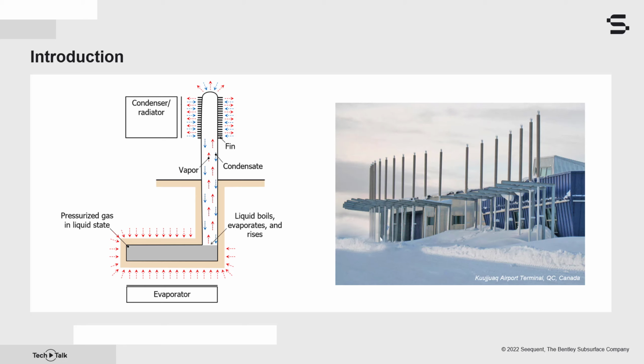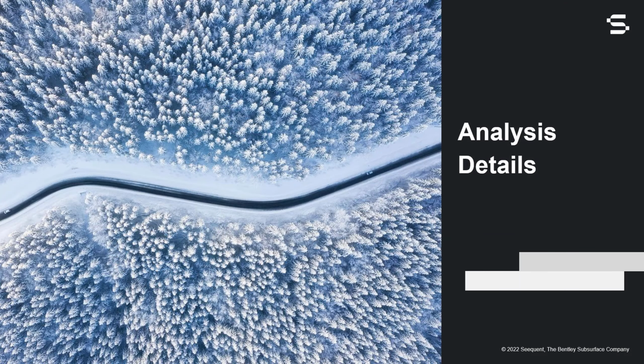the underlying permafrost. To model thermosyphons in GeoStudio, we added cylinders representing the evaporators to the project geometry during last month's Tech Talk. The thermosyphon boundary condition available in Temp-W and Temp3D, which computes the convective heat flux using Newton's cooling law, will be applied to the outer surface of the cylinders. Let us review the project in greater detail before starting our work in GeoStudio.